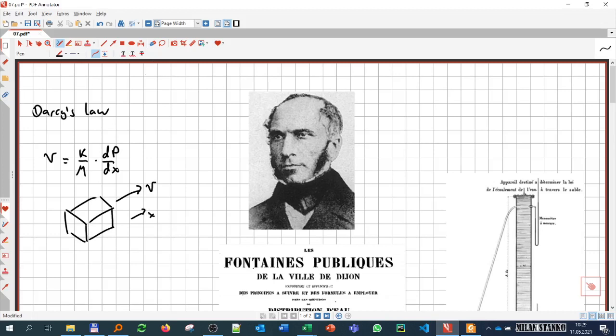That tells you essentially that the pressure drop across that slab, or that porous media, depends on the velocity. If I have a higher velocity, I will have a higher pressure drop. It also depends on the properties of the fluid, on the viscosity, how many losses the fluid causes when it flows, and on some property of the porous media, of the rock, that tells you how difficult it is to flow, how many obstacles you have in this porous media.